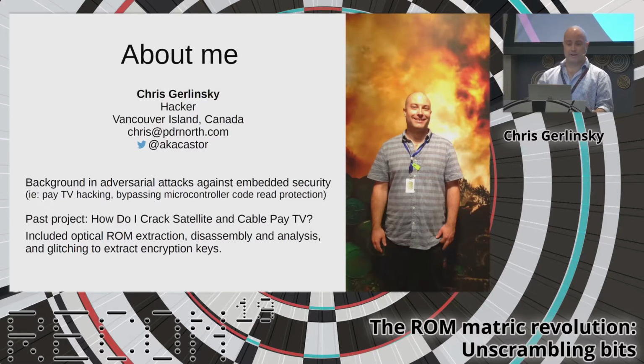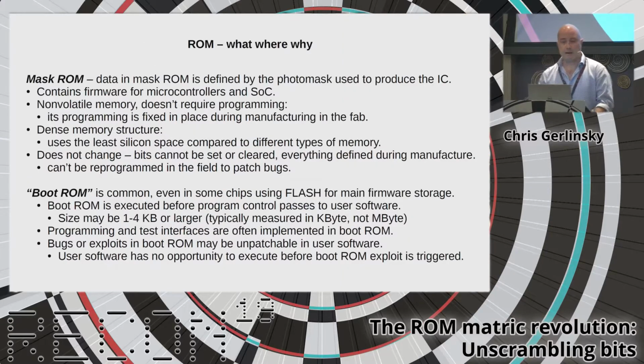As mentioned, a past project that I presented at RECON was about cracking satellite and cable pay TV. And in that project, I did an optical ROM extraction from a chip, disassembled it, analyzed that, and was able to glitch and extract the encryption keys. So today I'm going to talk about descrambling data from mask ROM.